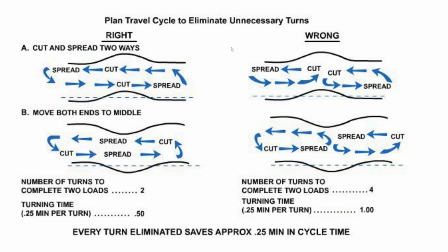Let's talk about how we plan operations with our scrapers. Scrapers are efficient vehicles when they're moving straight ahead, and they're less than efficient in situations where you are moving them to turn. And so you want to plan your travel cycles in such a way that you are eliminating the turns.